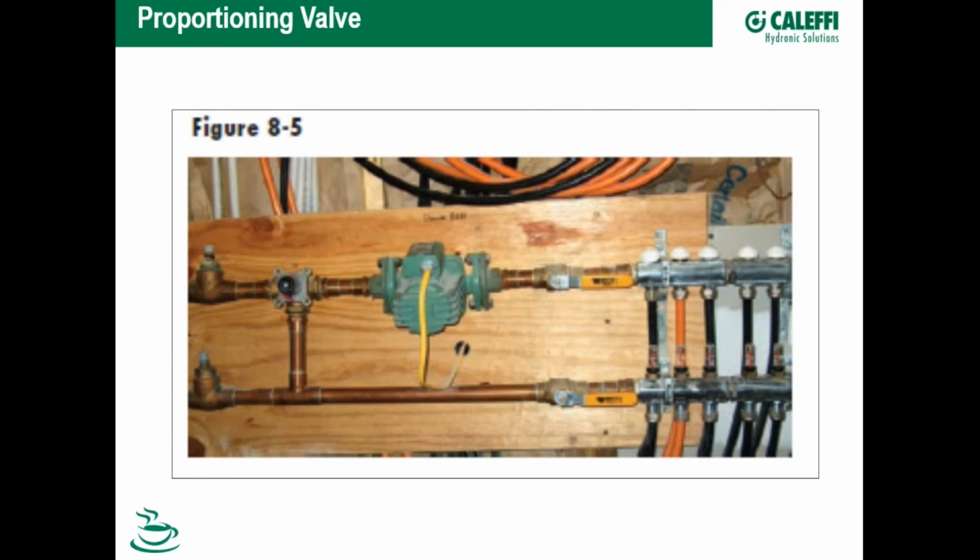And I've had guys say, you know what, I want to do radiant heating, and then they come back maybe a month later and their question is, Jody, how do I lock the water temperature in at 90 degrees or whatever number they happen to have? Guys that know me know that I'm a big fan of outdoor reset control, but the reality is it has to be a mix of technology, because when the day is done, it is about driving comfort in the eyes of the homeowner.